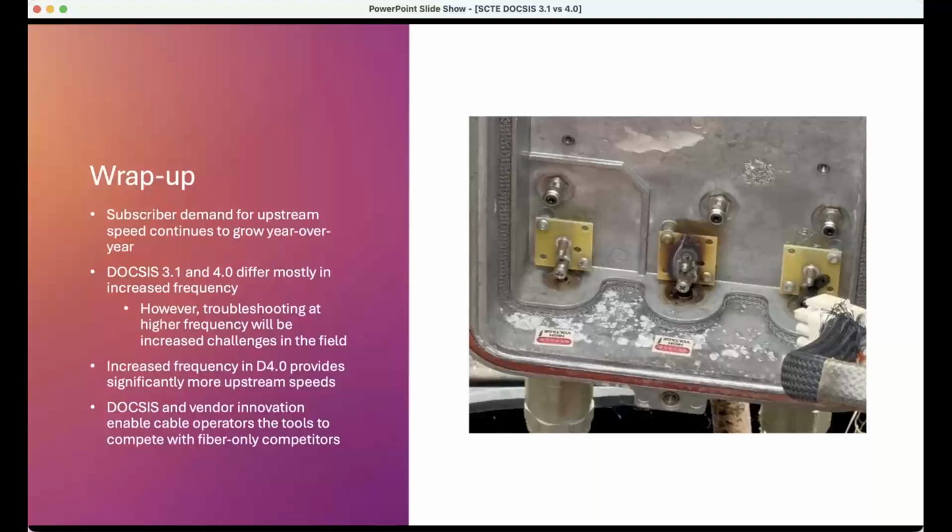How does it work when there are multiple orders of modulation in a single profile? Comcast does this a lot. Example, profile B having 1K and 4K 256. Yep. So, that is the way all OFDM and all OFDMA channels work. They're going to have multiple profile options that are available for the cable modem to use. Let's say 256, 1024, 4096, 3 profiles.